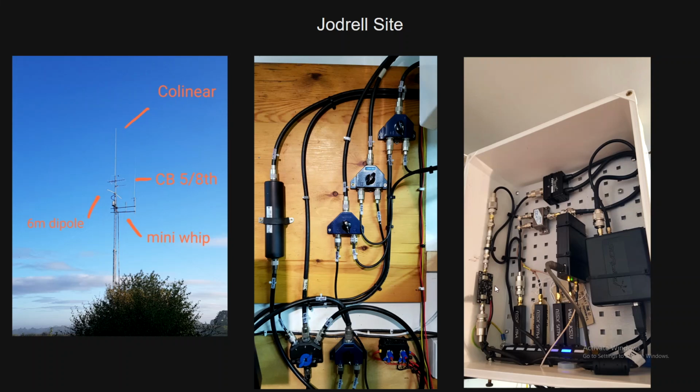So that's a bit better for signal to noise on UHF and VHF, and it has made a bit of a difference actually. These are 6 dB pads because the gain from the preamp is just too high. The poor old RTL dongles can't cope with having that much gain. They just completely overload, and you get loads of ghosting and things like that. So I've had to attenuate it. So we've got a total of about 12 dB attenuation there. You get about 4 dB attenuation with the splitter. So yeah, it's been required.